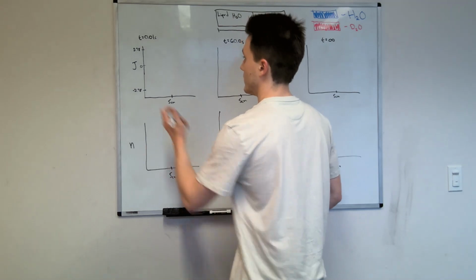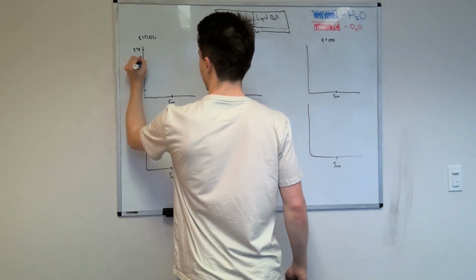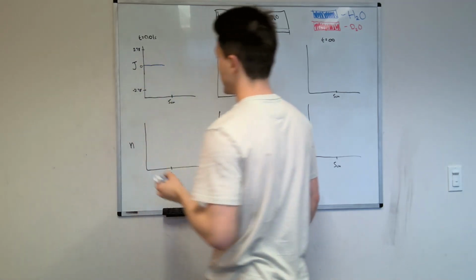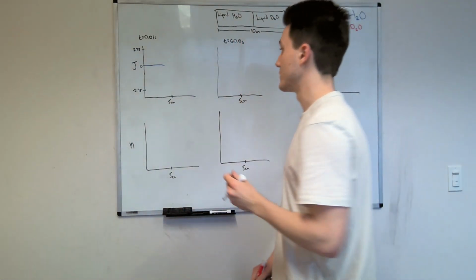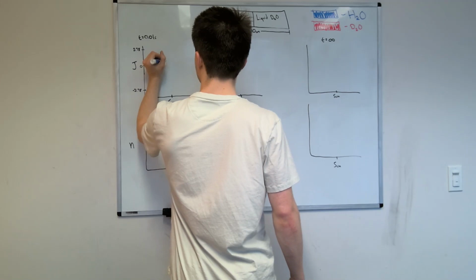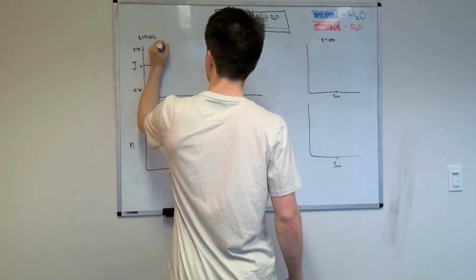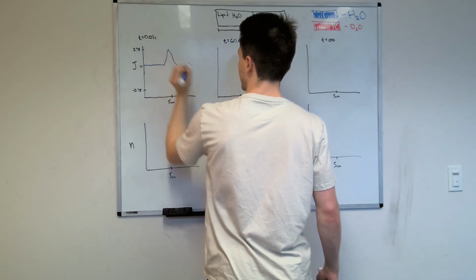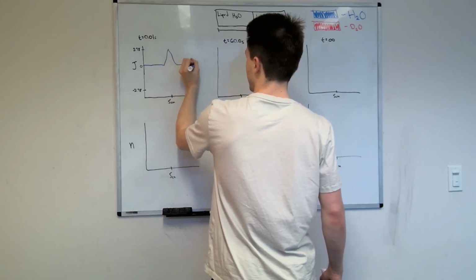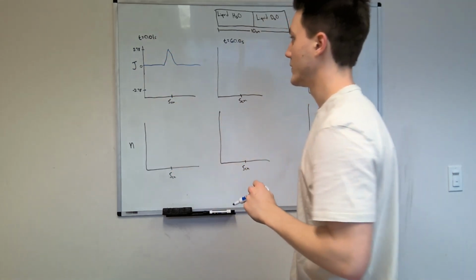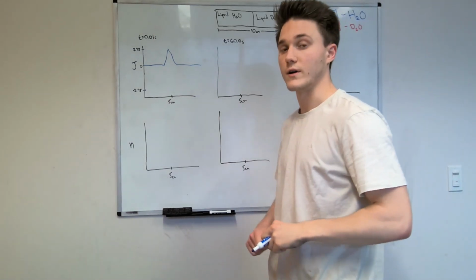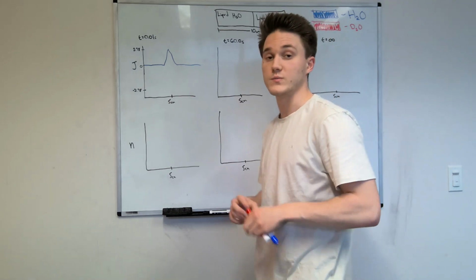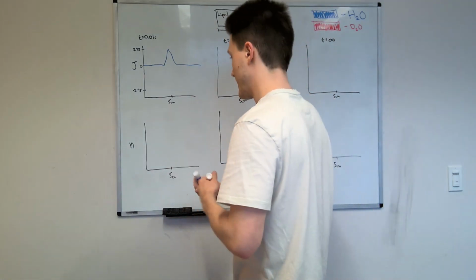Initially, water does not have any molar diffusive flux until it reaches about the 4 centimeter mark, where it goes up to 2.78, then back down to 0, because the water hasn't been given the chance to disperse that far into the tube yet.